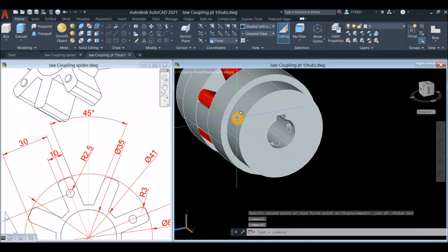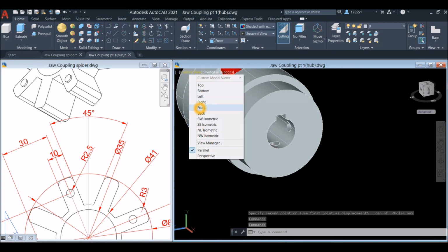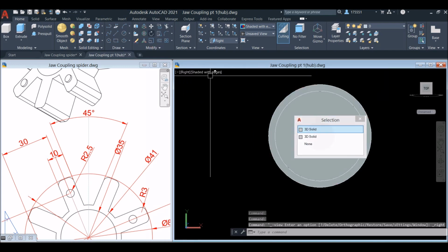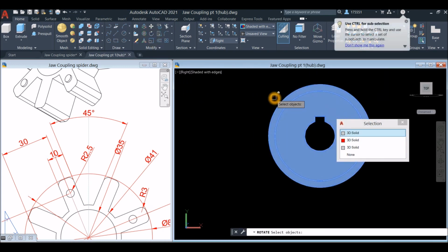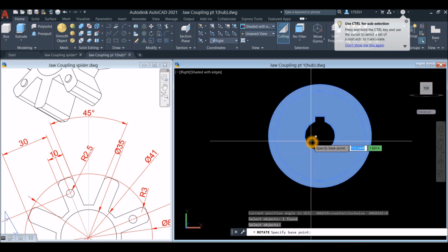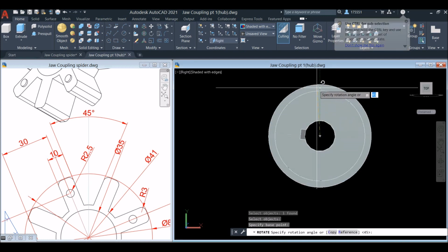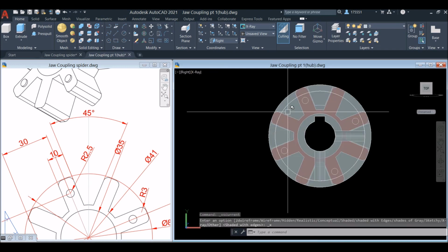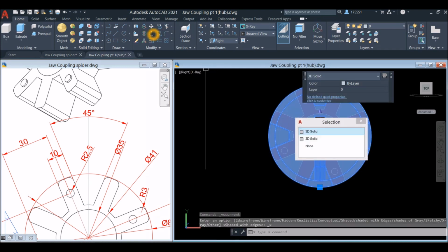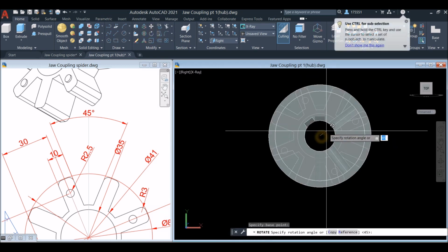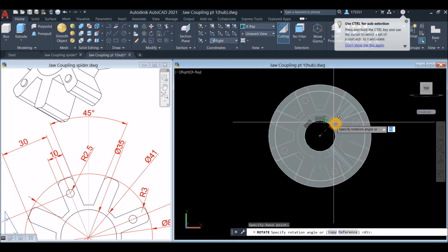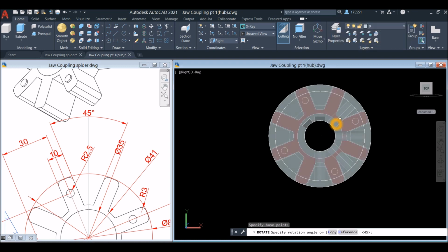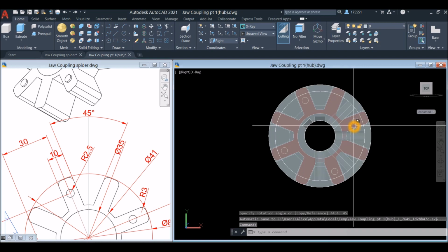And bring your drawing to right view. And turn this one. Select. Specify center point. And rotate for, just give me a sec here. I'm going to change this to X-ray. Okay, so rotate this one. Specify center. And I think it's 45 degrees. Yeah, it looks right.